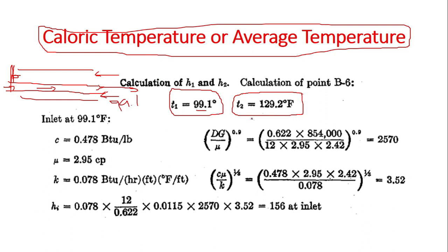When determining the fluid properties for the cold fluid, the question is what temperature we will use, the inlet temperature or the outlet temperature. The temperature is important because from it we determine the fluid properties.